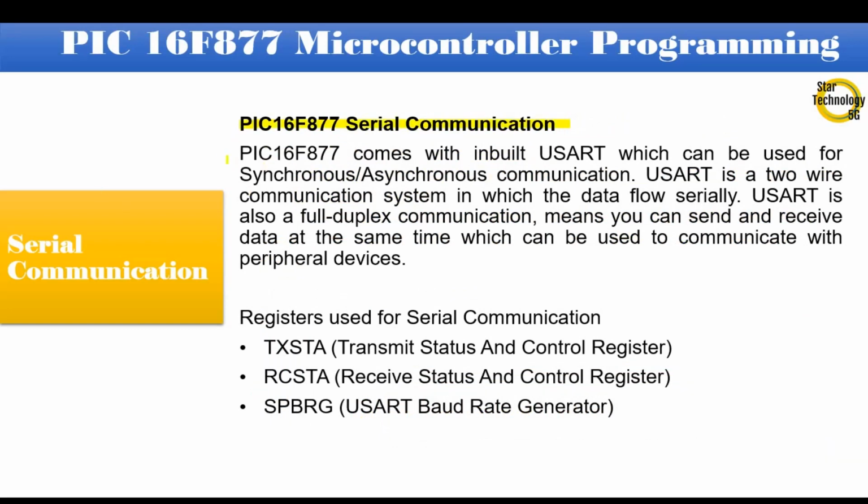PIC16F877 Serial Communication. PIC16F877 comes with an inbuilt USART which can be used for synchronous and asynchronous communication. USART is a two-wire communication system in which the data flows serially. USART is also a full duplex communication, which means you can send and receive data at the same time, and it can be used to communicate with peripheral devices.